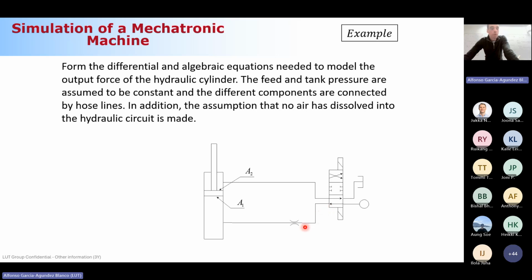This is another control volume and is basically consisting of this volume here, the volume of this hose, okay? And why do I stop here? Because I have here a discontinuity in the flow that is given by this valve. Remember that this is the symbol of a throttle valve, okay? We have studied three types of valve. One of them was the pressure relief valve that we studied not in much detail, but we studied two valves in detail, learning how to model the volumetric flow rates, which are the directional control valve here, okay? That can provide you different configurations, and this throttle valve, okay? Throttle valve that basically is accelerating the fluid, okay?